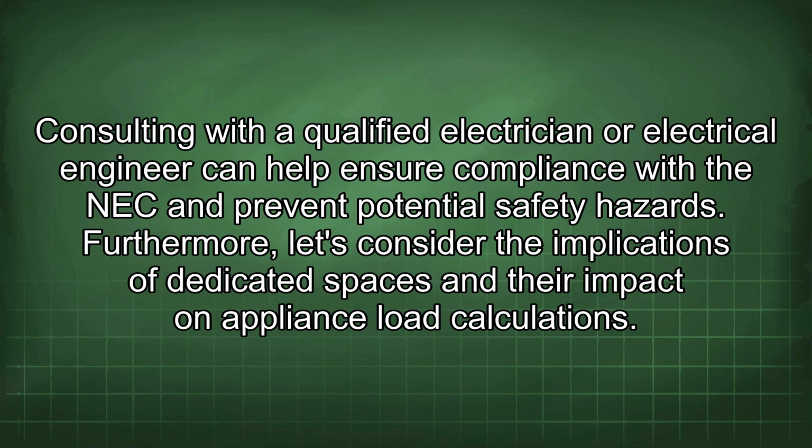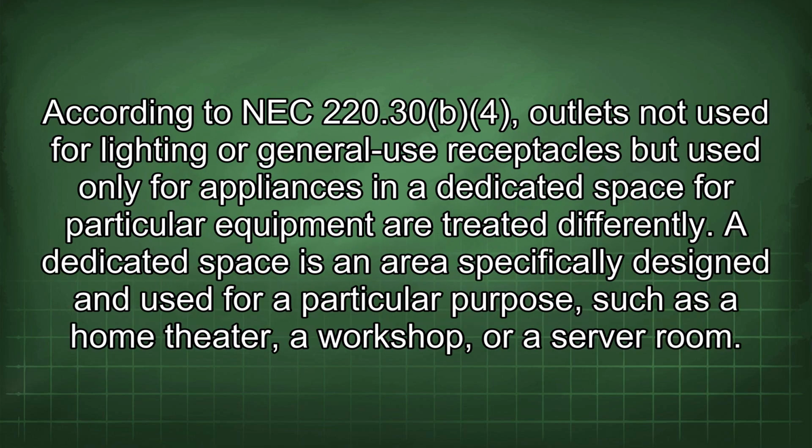Furthermore, let's consider the implications of dedicated spaces and their impact on appliance load calculations. According to NEC 220.34, outlets not used for lighting or general use receptacles but used only for appliances in a dedicated space for particular equipment are treated differently. A dedicated space is an area specifically designed and used for a particular purpose, such as a home theater, a workshop, or a server room.